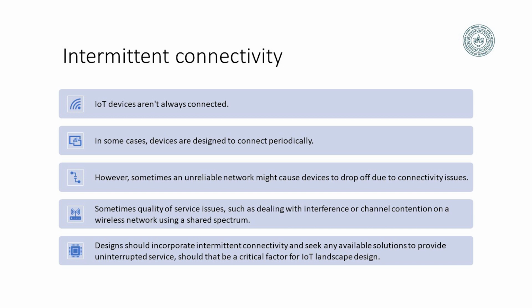If it is on all the time, then you are wasting the battery power, and you have to go in again and again to replace your battery, right? If it only turns on when there is motion detected and then transmits the data, then the battery can last for a really long time. So, you must send out data only as often as you need it.